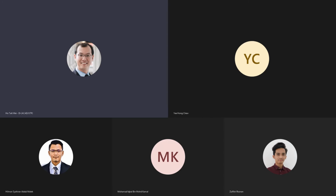But I've pretty much covered what I wanted to cover on SDRAM today, and the remaining is just to give you an intro on FPGAs and how to program them. But I'm doing it more by telling you what's inside an FPGA. It's not that much. Once you understand what's inside, it's basically a lookup table and flip-flops. And once you understand that, you'll know how to program it, right?